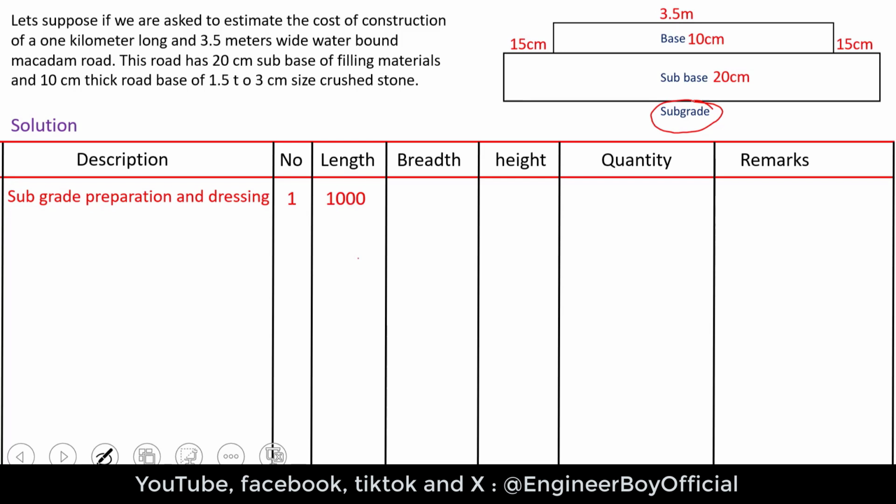Now the breadth of subgrade: if you see in the diagram, it is 3.5 plus 15 centimeters and 15 centimeters to the other side. That means the breadth of the subgrade should be 3.8, because we have 3.5 and we add 15 centimeters to both sides.